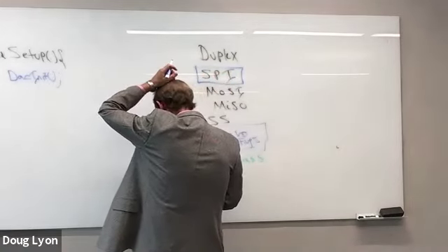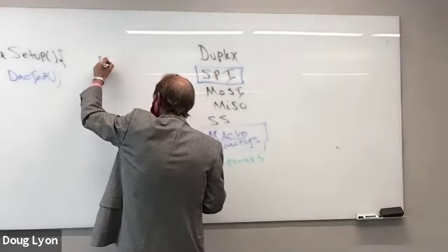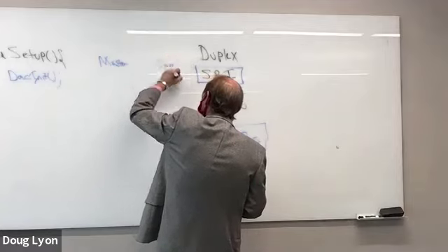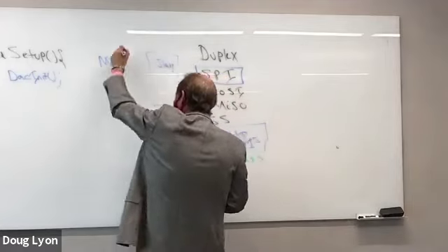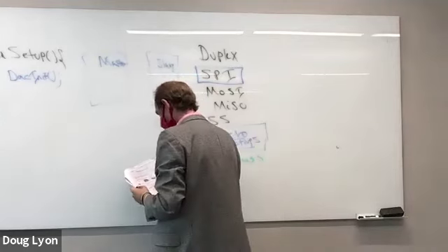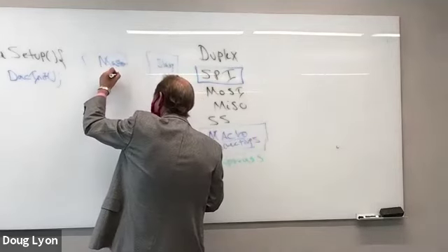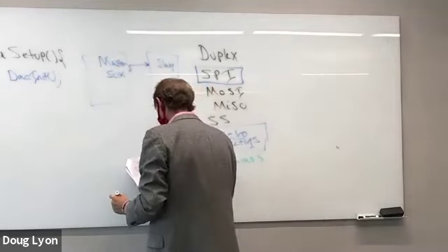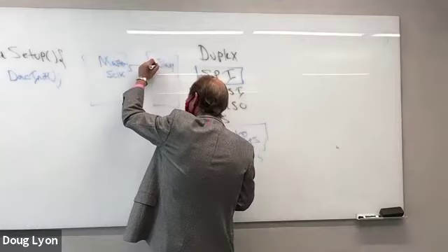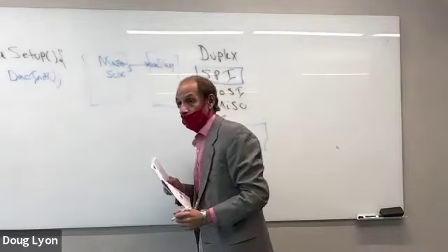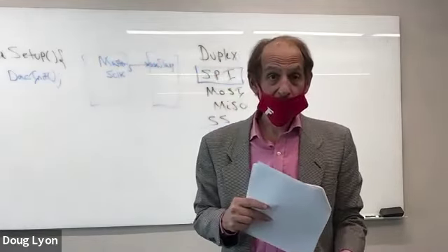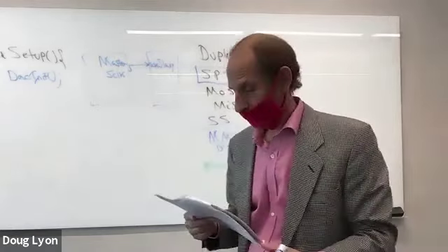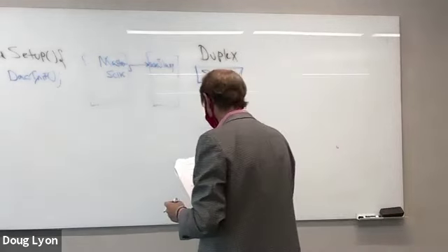Synchronous serial interface means you're going to have, in this case, a master and a slave. The master is going to have a serial clock. This is what makes this synchronous. Right? And there's going to be a serial clock input on the slave. You want to do fast communications to something like a digital to analog converter, you might as well make it synchronous, right? Because you're going to be outputting data really fast.